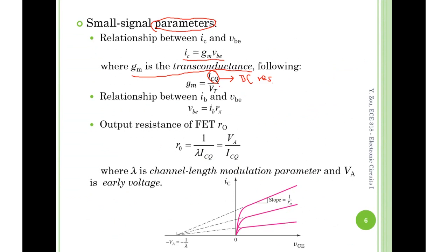And the denominator here is the VT. What is VT? Anyone remember this? That's the thermal voltage. Good. Again, more than one student knows the answer. Good. Thermal voltage. And what's the value then? It's about 26 millivolts. Right? Be very careful. It's millivolts. Okay, so it's not volts.